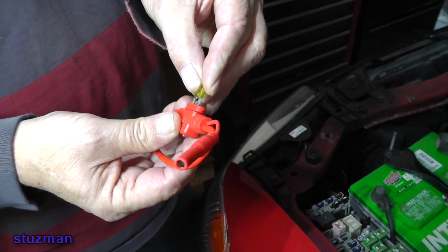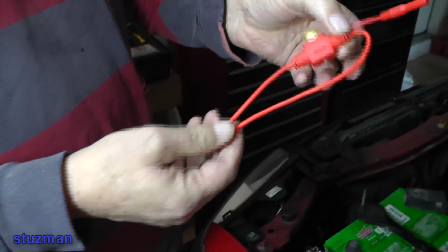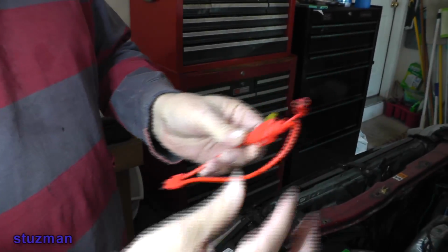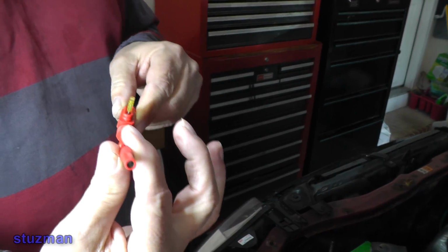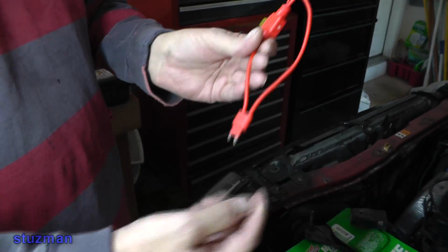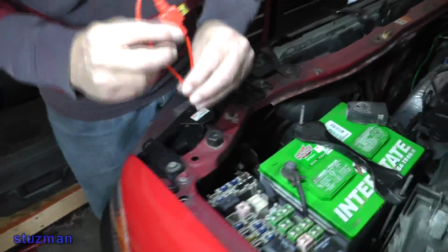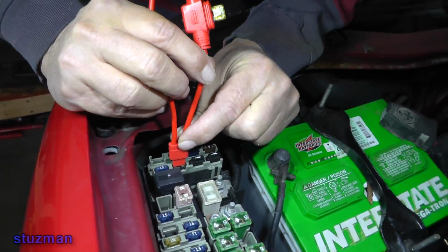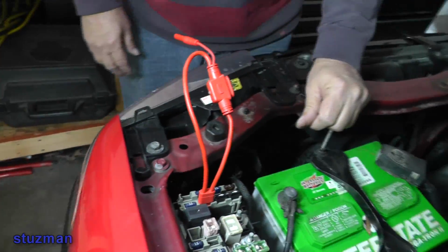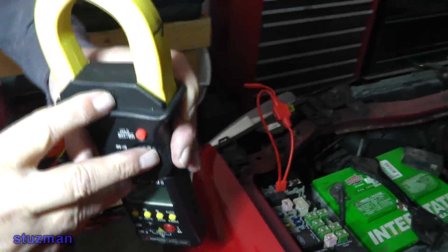Okay? Now I'm going to take the 20 amp fuse that we pulled out, and I'm going to stick it in this little component here, which allows you to get an amp clamp around, and also has a test lead point coming out of here if you want to check your voltage. Okay. And now what we're going to do is take this and stick it right down into the fuse holder. So we'll stick it right down in there. Okay? Doesn't matter which way, it does not matter which way.